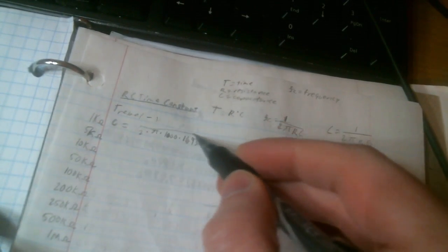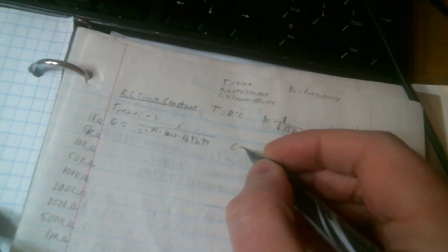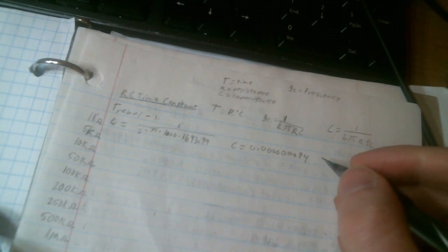So let's plug that into the calculator. That is, oops, forgot the over 1. That's important. So capacitance equals 0.123456794. So that would be a 94 nanofarad. I would probably round that up to 100, because you're probably going to get close to that anyway with tolerance. Could also bump that down to an 80 something. You might be able to find like a 90s.